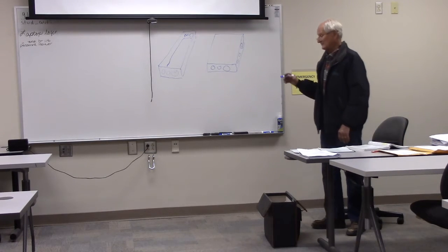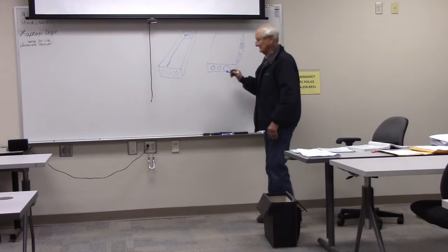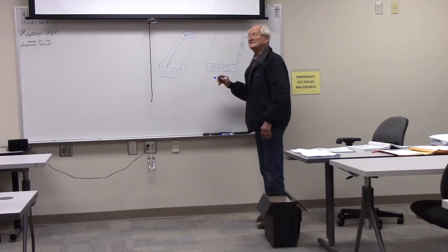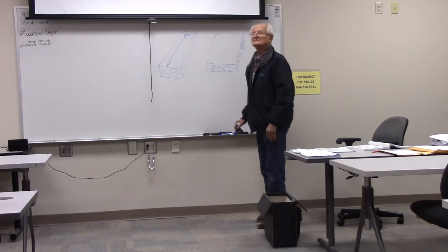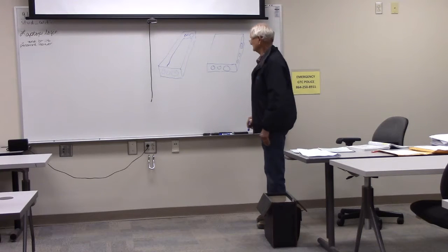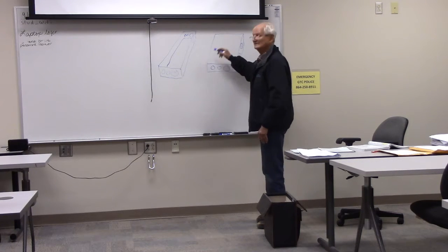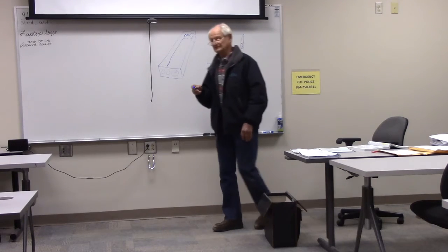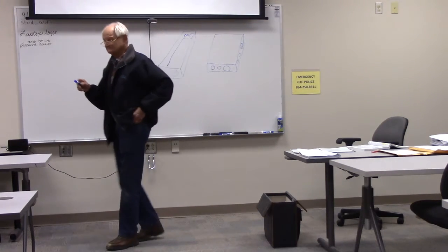So we've got a 3-inch and what? A 1-inch and a 1-inch. So 3 plus 1 is 4, plus 1 is 5, times what? 6. Say it loud. 6. So what does this box need to be? 30 inches square, right? And now, I mentioned this as we were going over the text.